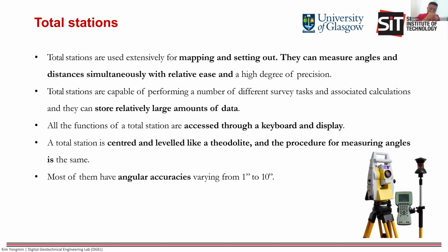All the total station functions are accessed through a keyboard and a display panel. You can control it by keying on the keyboard, and the data will show on the display screen for you to take down the readings. The total station is centered and leveled like a theodolite.